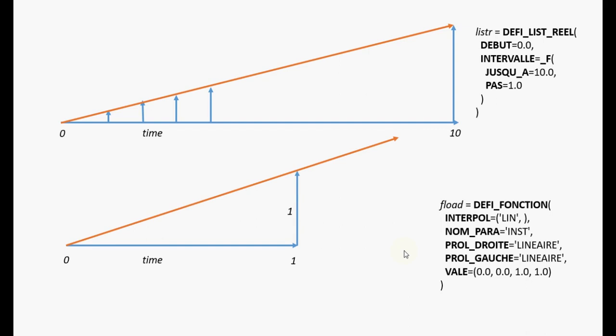Similarly, we will also define a function for load that will be multiplied for each analysis. By this, what I mean is that the force function will be increased according to the DEFI_FONCTION, while the analysis itself will be based on the LIST_R. Okay, hopefully it is a bit complicated right now, but it will be clear as we do the analysis.